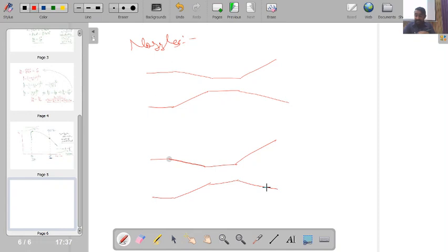okay, so say I have these two nozzles. So in the first case, if I have over expansion, this P exit, say this is back pressure PB, so P exit will be lesser than PB in case of over expansion. So ultimately what will happen, I will find that here I will have formation of an oblique shock wave. Okay, and in this case you will find that the flow streamline will move something like this.